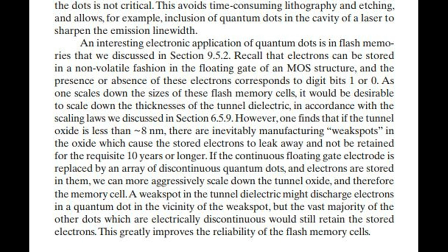An interesting electronic application of quantum dots is in flash memories that we discussed in section 9.5.2. Recall that electrons can be stored in a non-volatile fashion in the floating gate of a metal oxide semiconductor structure, and the presence or absence of these electrons corresponds to digital bits 1 or 0. As one scales down the sizes of these flash memory cells, it would be desirable to scale down the thicknesses of the tunnel dielectric, in accordance with the scaling laws we discussed in section 6.5.9.